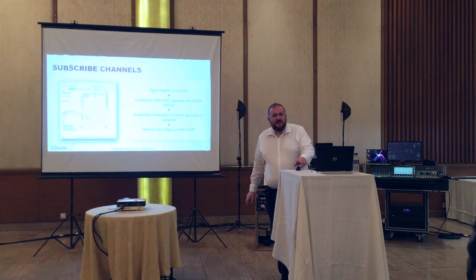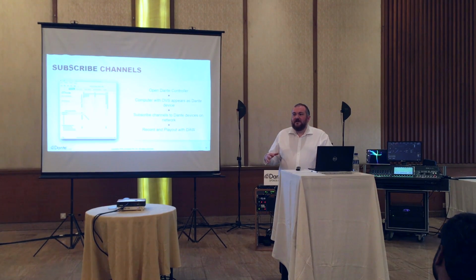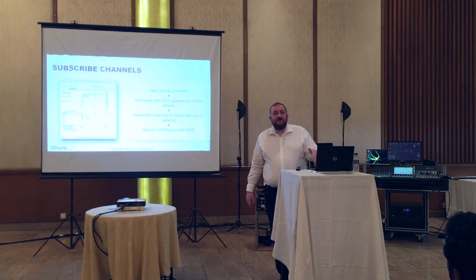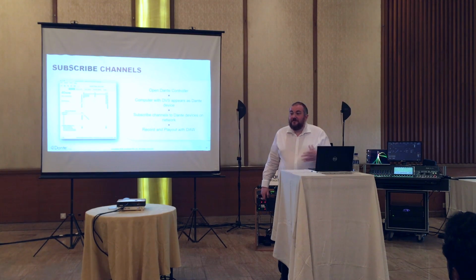A few people have asked, well, at 4 milliseconds latency, what if I'm trying to record a band and I'm doing a front of house mix and a monitor mix, and I just want to add the laptop and take a split, and I want to send multicast to them all? Does that mean that the latency of that channel goes up for everybody? Well, it will stick at 1 millisecond because it's easier to record samples in packets than it is to produce them. So receiving, we can receive at 1 millisecond, but transmission will be stuck at 4 milliseconds with Dante Virtual Soundcard. It's not magic, it's just it doesn't get explained well anywhere.